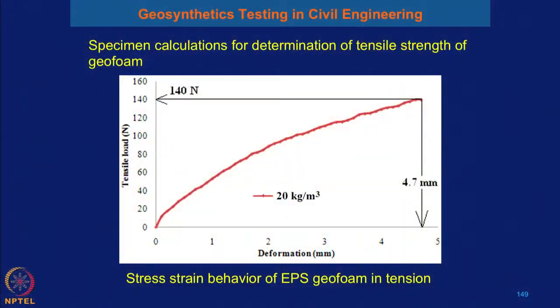From this test, you can draw a correlation between the tensile load and the deformation, or you can say this is the stress strain behavior of EPS geofoam for a particular density of 20 kg per meter cube.